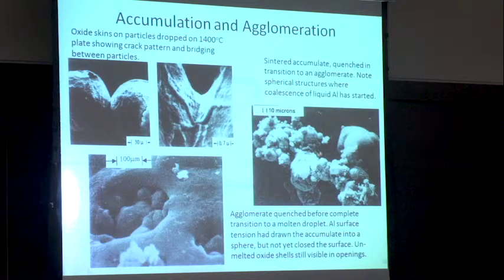And eventually you'll find that the aluminum starts to melt and engulf those primary particles, and you get these larger particles, which are basically your aggregates that form and eventually come off the surface. And here's a picture of the original particles starting to be engulfed by molten aluminum around them. That's going to be lifted off as a much larger particle.